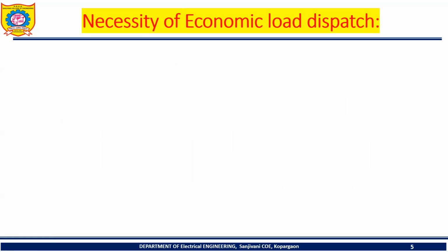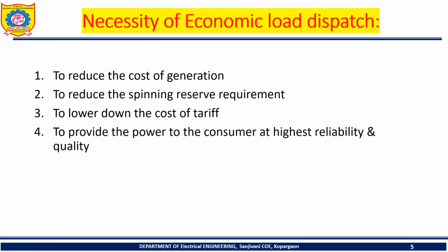Now, there will be a question in our mind, why are we going to study economic load dispatch? What is the benefit? Ultimately, all the aim should be going for the economy. So what is the necessity of economic load dispatch? Here, one by one we are studying. First one, to reduce the cost of generation. Overall cost of generation is going to be reduced when we are dealing with economic load dispatch.